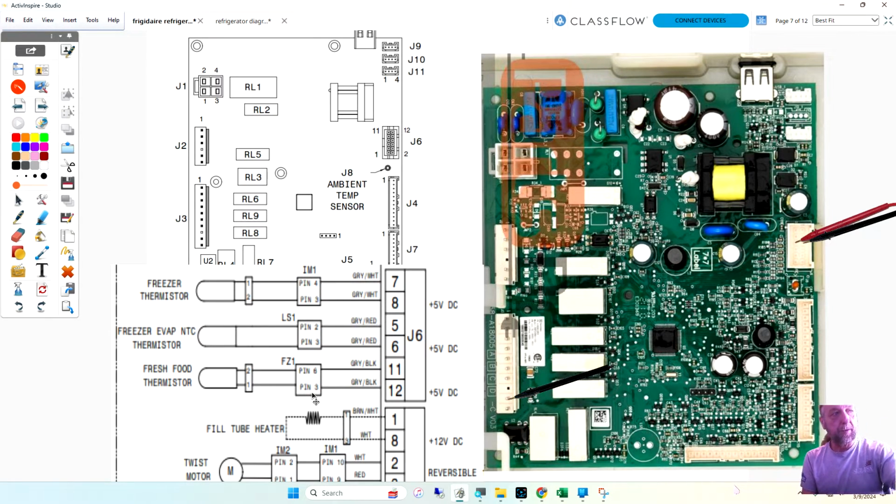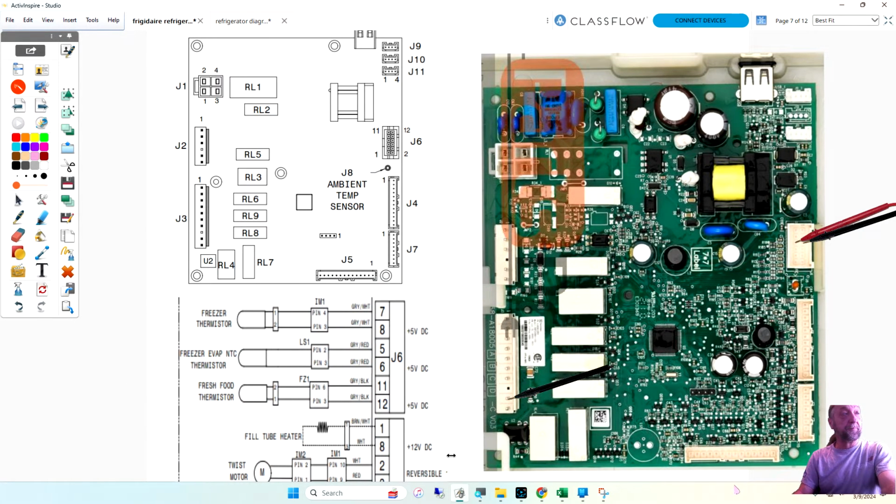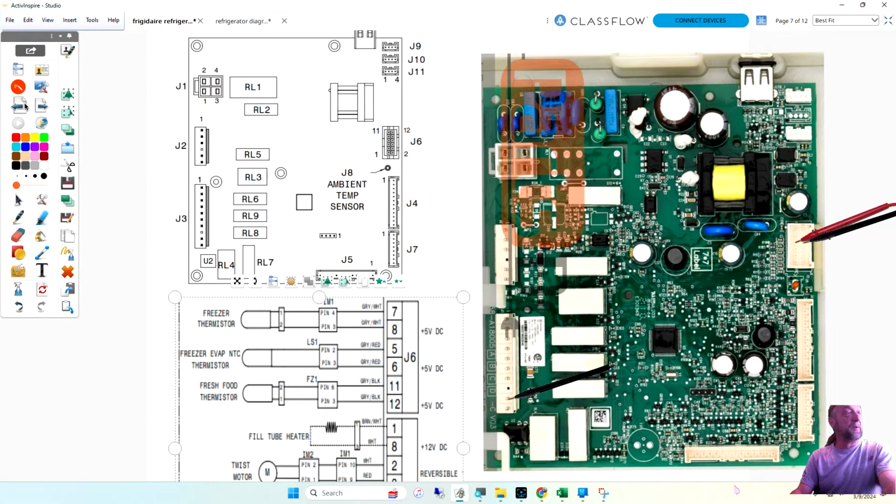Did it tell the temperature from the bottom tray with the food? Not quite. It tells the temperature of the refrigerator, yes, but what is it telling the board to do? Is it going to tell it to turn the compressor off when the fridge is cold? It is to control the damper for the air flowing from the freezer into the refrigerator.